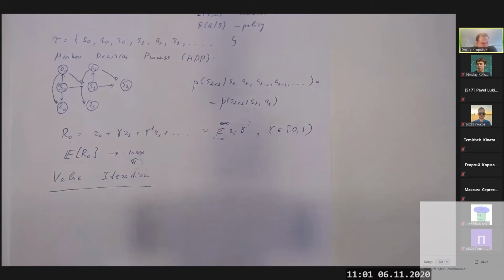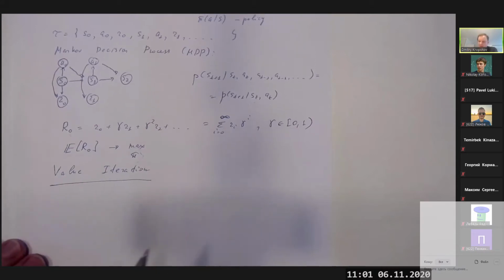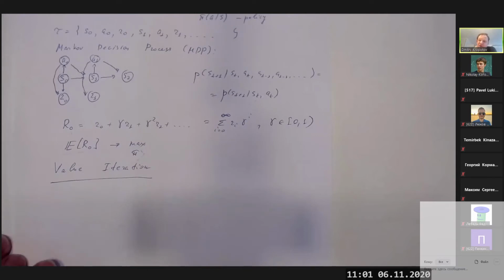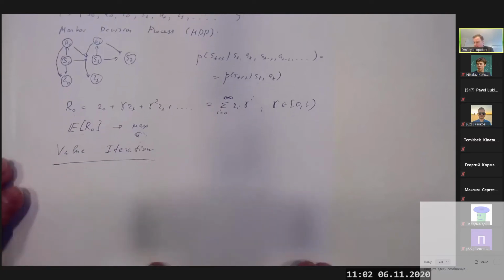And in dynamic programming, you usually introduce what is called the Bellman function. That shows you the optimal performance starting from a particular time moment, what you're able to get in the optimal trajectory. And this Bellman function is usually denoted by a V function. That is how Bellman denoted it in his articles on the dynamic programming algorithm.